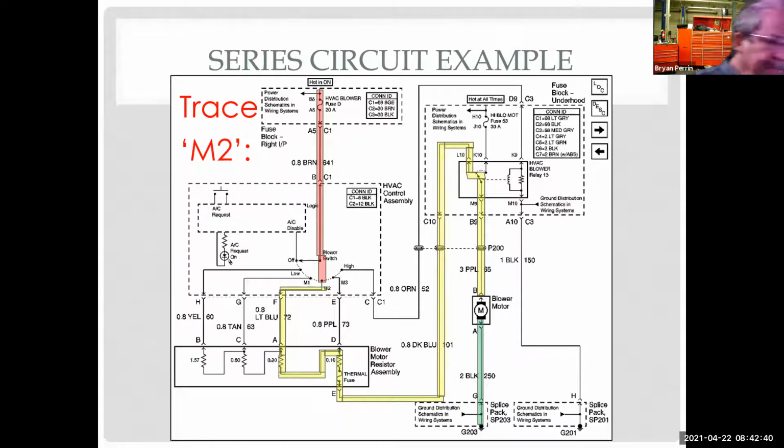It'd be like if I took a battery hooked up to my car, and that's my power supply. Then I take another wire to a light bulb, connect the light bulb to the positive side of the battery. The ground side of the light bulb isn't touching anything. And then I go and check the voltage at that wire. I would see all my battery voltage because it's gone up the wire, through the light bulb, up and stopped. So I'd see all that battery voltage at the end of that wire. Same thing's happening here.